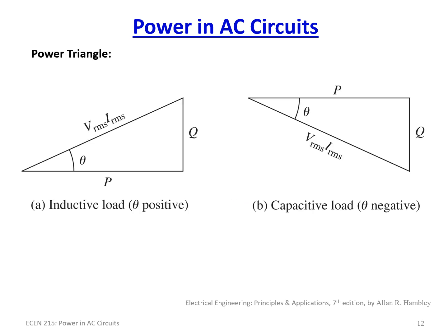And here is what is known as the power triangle, so you can see what this actually means visually. For an inductive load, theta is positive, meaning that the current is lagging behind the voltage. Theta V minus theta I is positive. The phase angle on the voltage is greater than the phase angle on the current.